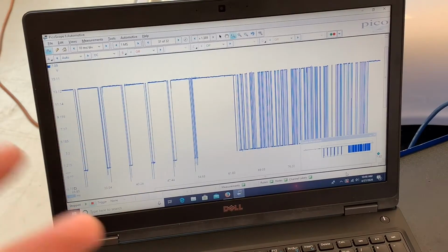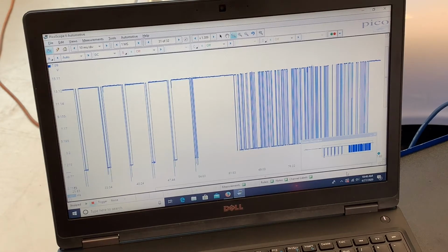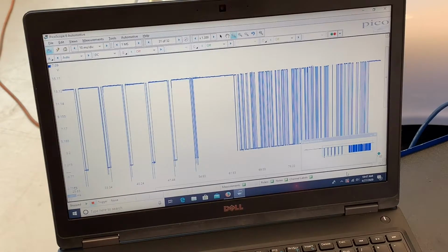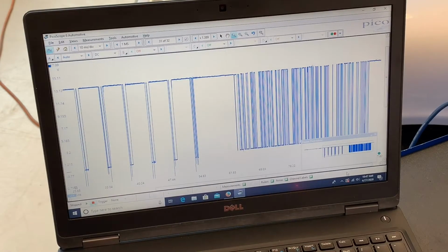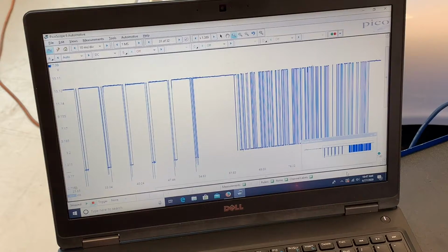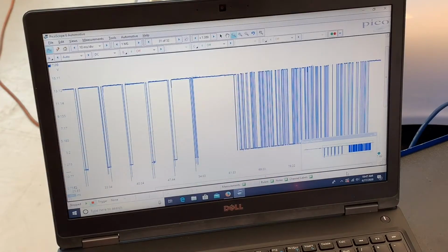The on-off ultimately translates to 0s and 1s, which helps me translate that computer language so that we can communicate things like engine RPM or the ECT value, the things that are on my scan tool screen right now. That information is all in this packet that you see on the screen. At the automotive technician level, we really don't look to understand exactly how to break these down. If you get into the engineering side, there is software you can get to decode this information, so we understand exactly which piece of this packet is RPM.